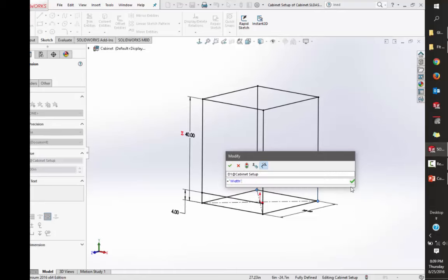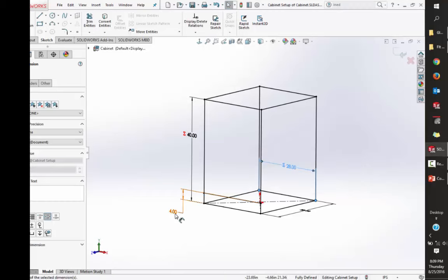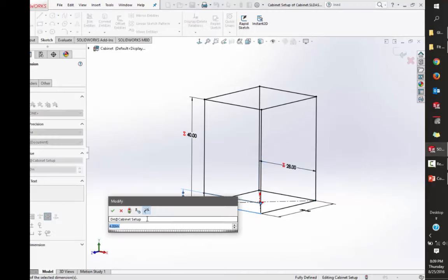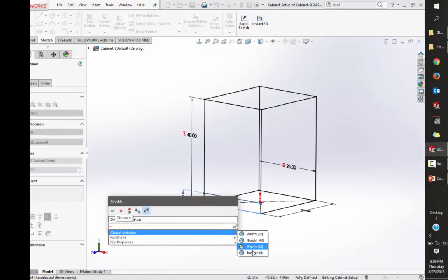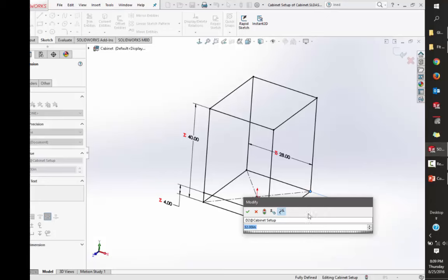And yes, if you know what you wrote in here, you can put equals, quotation, the name, quotation, and you can actually connect it up. You don't have to pick it from a list if you don't want to. So I'll accept that one. You can see that the sketch is already updated. I got the toe plate area here, R, and then we'll hit equals. And then we'll do the last one here, which is the depth. That's going to equal the depth.